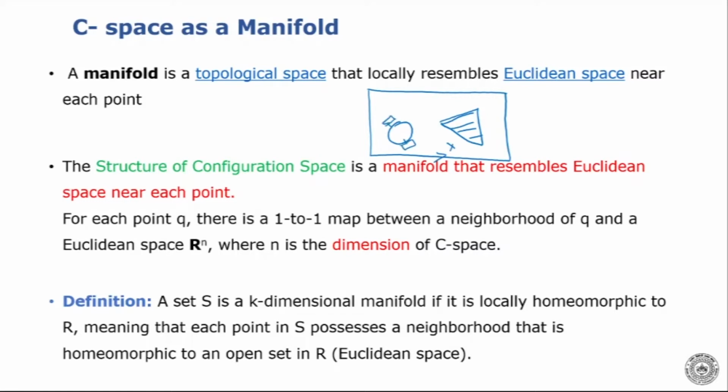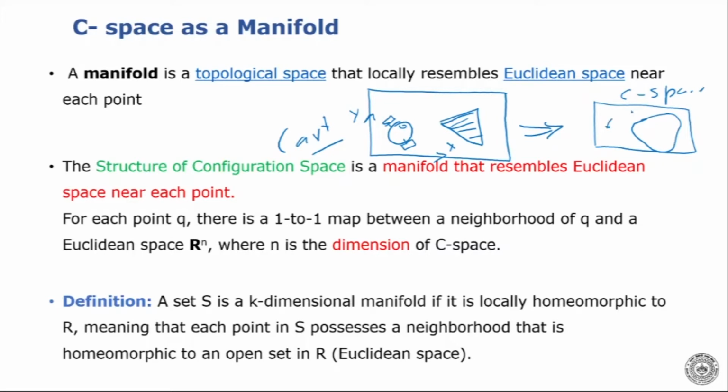From the Cartesian space, we move to the C space, in which the workspace becomes smaller and the obstacle becomes larger, like this, and the robot becomes a point. Then in this C space, we find a path from the initial point to the goal point, maybe like this.